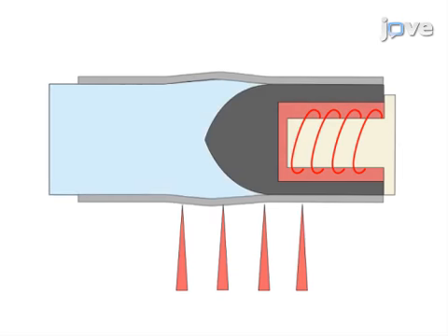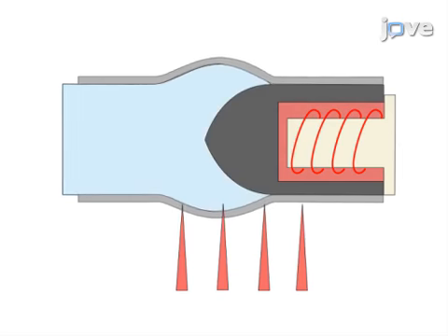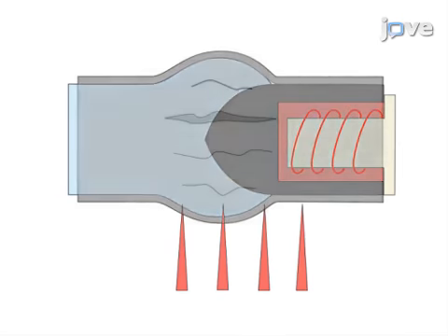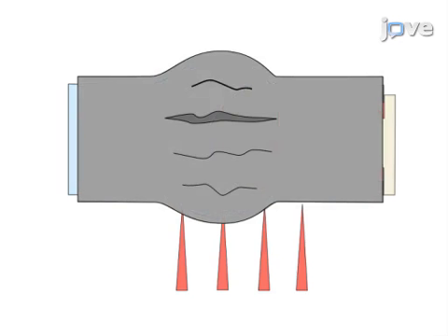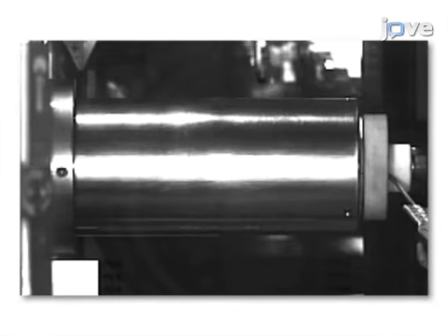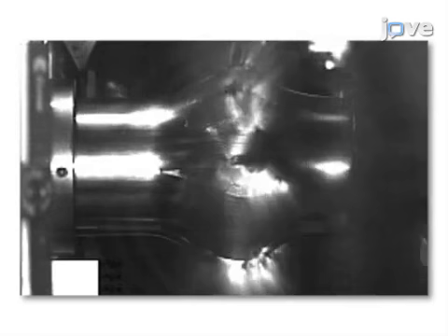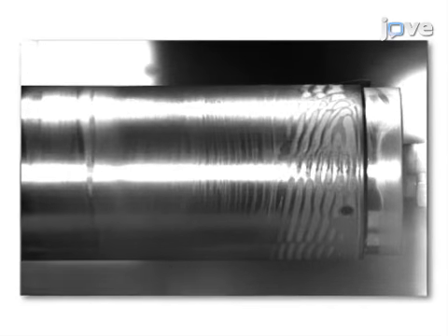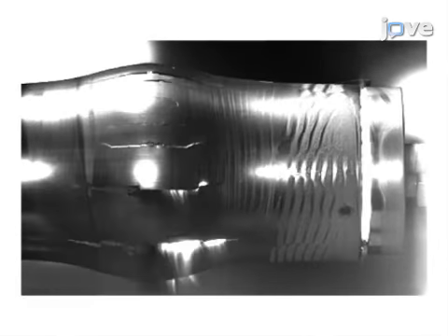The resulting impact between the projectile and the ogive insert causes the polycarbonate to flow outwards, driving the cylinder into uniform radial expansion, which creates a tensile stress state around the circumferential direction. The velocimetry and high-speed imaging can then be used to determine the deformation, failure, and fragmentation characteristics of the material with temperature, along with fragment analysis to ascertain the fracture mechanisms.